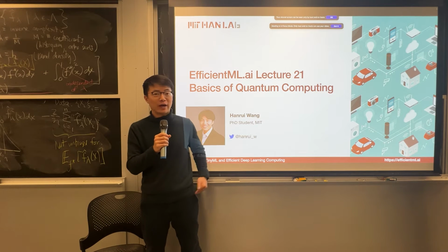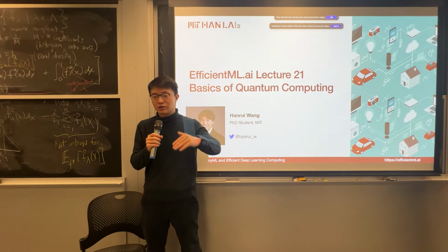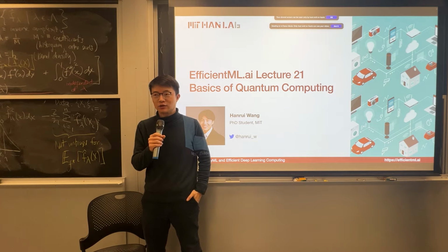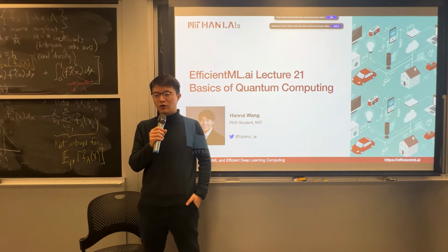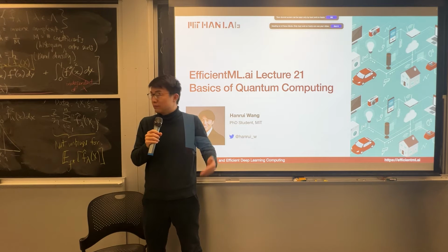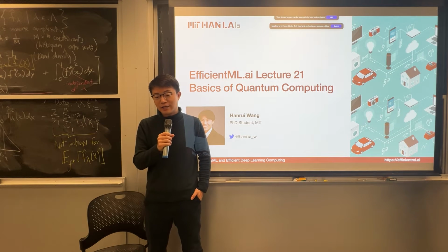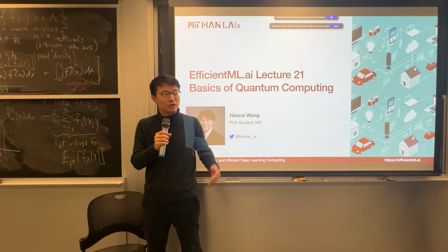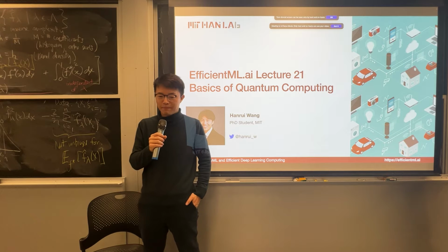He also designed the Spartan accelerator, which we talked about, to look at the sparsity in the token dimension by looking at the attention map. If they're small, then we prune the whole column. That is actually the most cited paper in the past 4 years of the HPCA conference. Recently, in collaboration with Atlanta, he also taped it out as a chip, a Spartan chip.